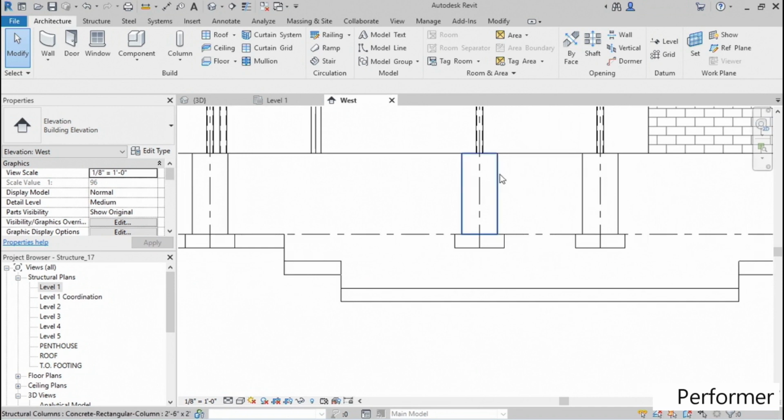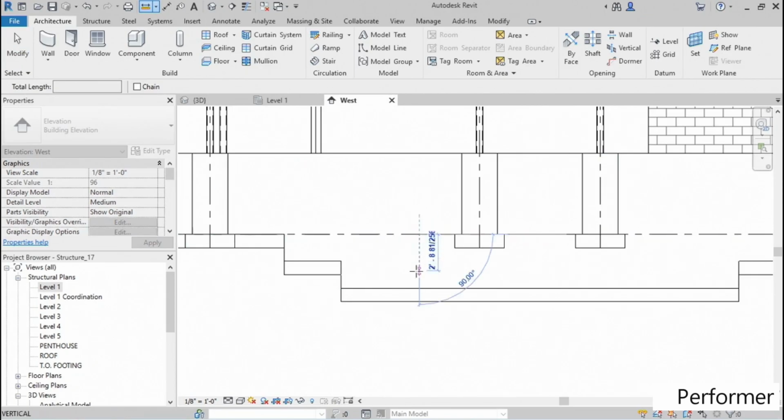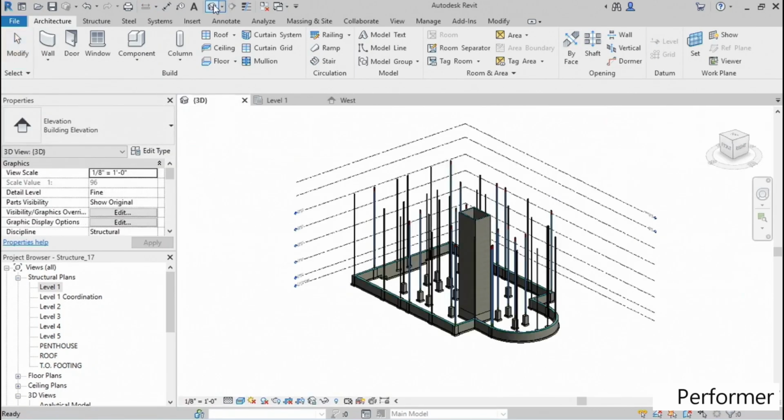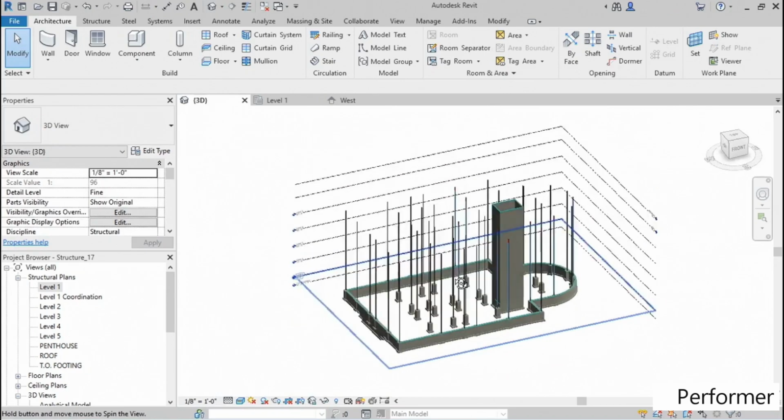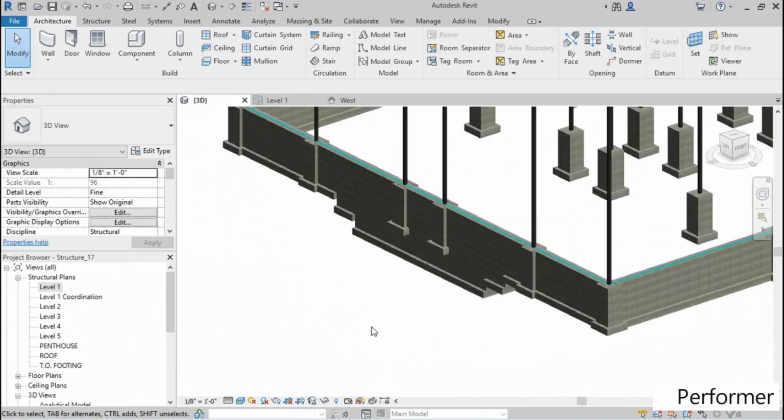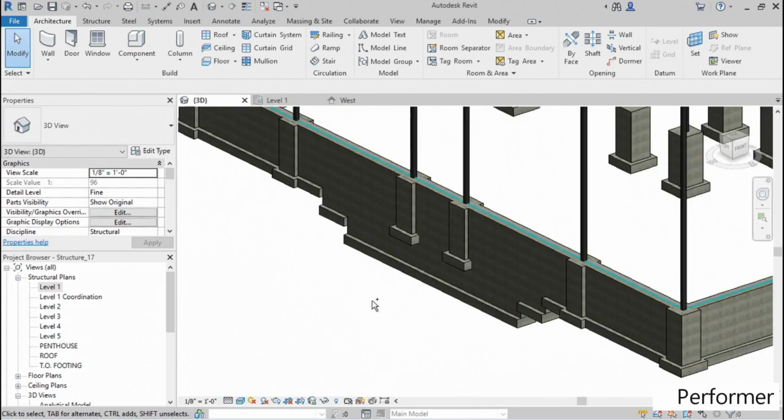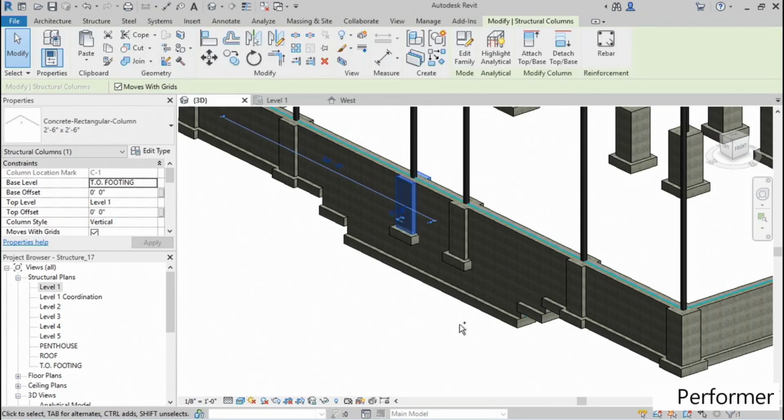The problem is that our piers are not going down far enough. So I'm just going to take a distance. I'm guessing it's going to be 4 feet. We need to offset these 2 piers down 4 feet. Let's go to 3D view. Scroll around to the back of it. Hold down your Control key. Select that pier. Then select that pier.